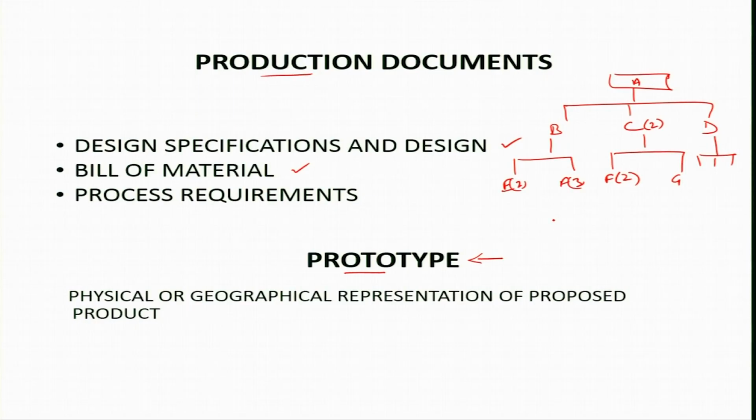These techniques are given alternate names, like 3D printing, or additive manufacturing. Even a single component can be produced in the most economic manner, and this is also called rapid prototyping. Nowadays these machines are available where earlier the material used was mostly plastic, but now metals, ferrous and non-ferrous, can also be used in these machines to create prototypes, and they can be as good as the final product.